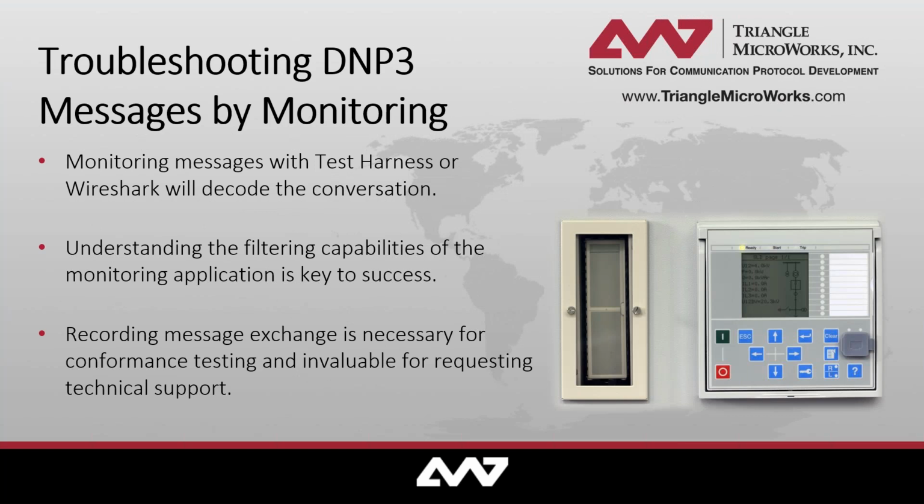In the last example, we were able to simulate one side of the communications, but sometimes you need to be able to decode communications between two real devices, or you are unable to simulate either one to recreate a problem. This is when you can use monitoring to help you diagnose the issue. Monitoring is the act of listening or sniffing the wire to gather information about communications on it.